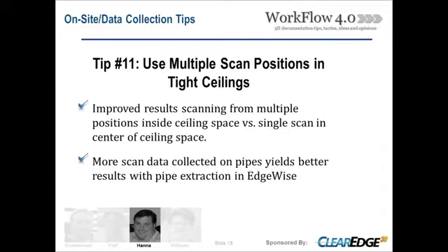If we're in a room, for instance, we're scanning maybe 3 to 5 positions up in the ceiling plenum space to ensure that we're getting adequate coverage. Again, we're thinking about modeling down the road, and it's critical that we get good results when we're running tools like Edgewise, and this really helps with that.